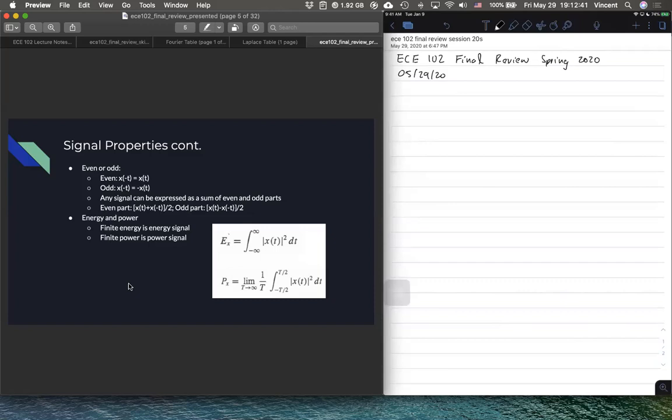Yeah, so my advice is to think of this more intuitively. For example, with the energy, you can relate it to things that you see in your circuits and physics classes. If you think about electromagnetics, you might learn that the energy is the square of the electric field or the square of the magnetic field. So this is a more generalized and mathematical way to think about it. If you learned in circuits that the power being dissipated on a resistor is I squared times R or V squared over R, it's the same thing, only say you have a unit ohm resistor.